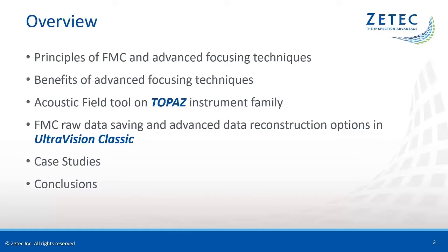This is our agenda for the webinar. First of all, I will briefly review the principles of the full matrix capture data collection process and some advanced focusing techniques like TFM and STF. After that, we will look at some live UT imaging on a reference block to illustrate the benefits of FMC and advanced focusing techniques, but also the conditions required to exploit the full potential of this technology.